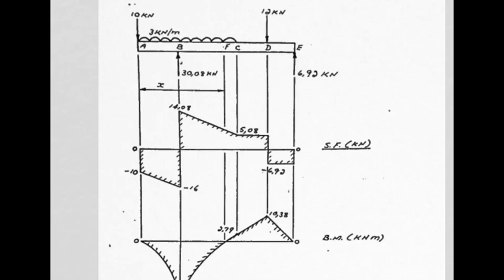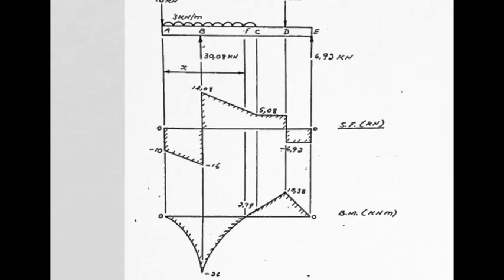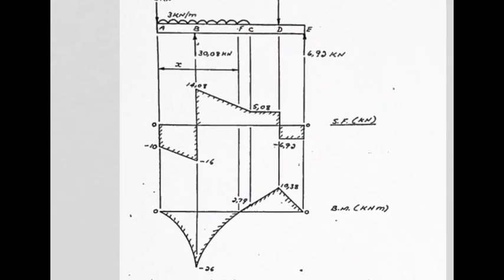Next is to decide where the bending moment will be straight and where it will be curved. Well, where there is not UDL, it will be straight, so you can simply join that point to that point with a ruler, and that point to that point with a ruler, and the reason for that is there are no UDLs in that area. However, between A and C, there are UDLs involved, so we need curves there.